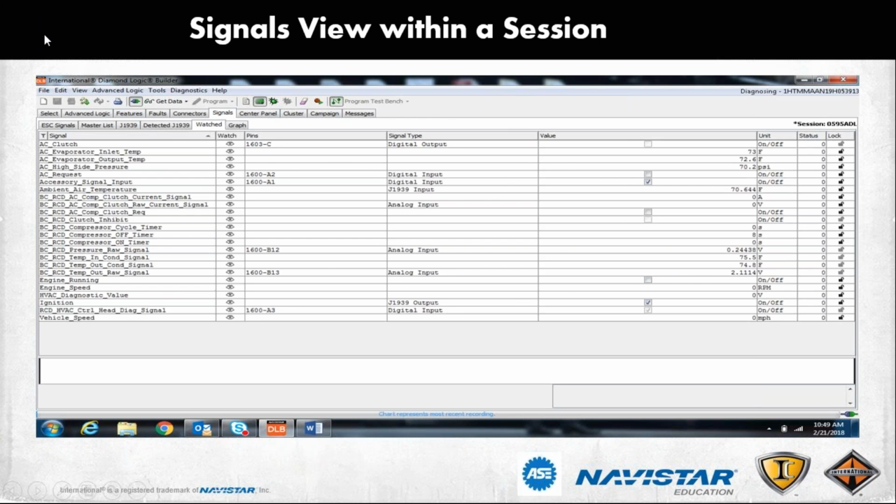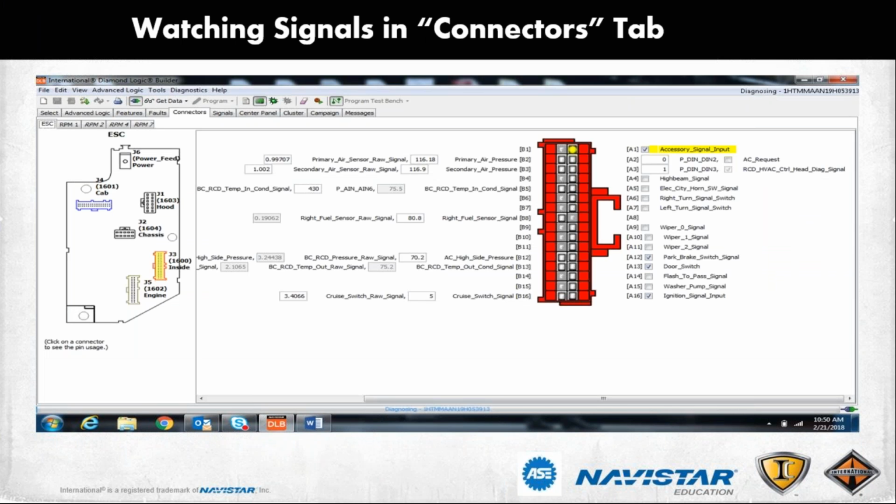Here we're going to wrap up. What is Diamond Logic? It is an electrical system that uses multiplex technology to provide control and communication between major functional areas of the vehicle, including the body. What does it do? Diamond Logic streamlines truck chassis and body equipment integration and performance. How does it work? Diamond Logic allows you to custom program the equipment parameters among a set of predetermined tasks. By automating functions of the truck, you increase the performance of the operation while reducing potential equipment damage, and you're enhancing safety.